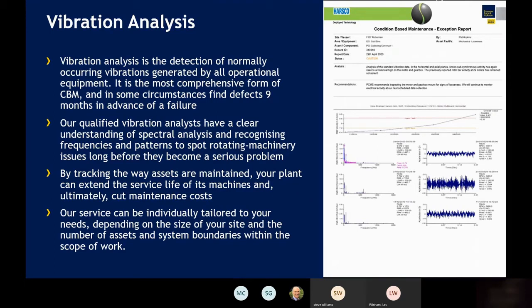We carry out vibration analysis. We do this because every fault within a rotating component produces a specific vibration signature. For example, an imbalance will create a different picture to a bearing fault. Highly trained engineers from both PCMS Engineering and Brammer, Buck and Hickman, using the latest data collectors and software, can recognize these patterns and accurately identify the cause and severity of the fault.